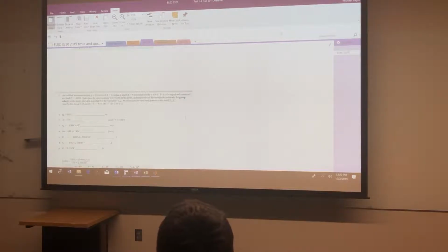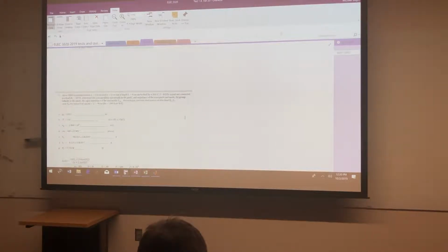Now, there's no source resistance, so you don't have to have Zn over Zn plus Rs times V source to get the value of the voltage just inside the waveguide. Does everybody hear me on this? I took the source resistance out of the problem to make it easy. You've got the value of the voltage just inside the waveguide there. Do you all follow me?